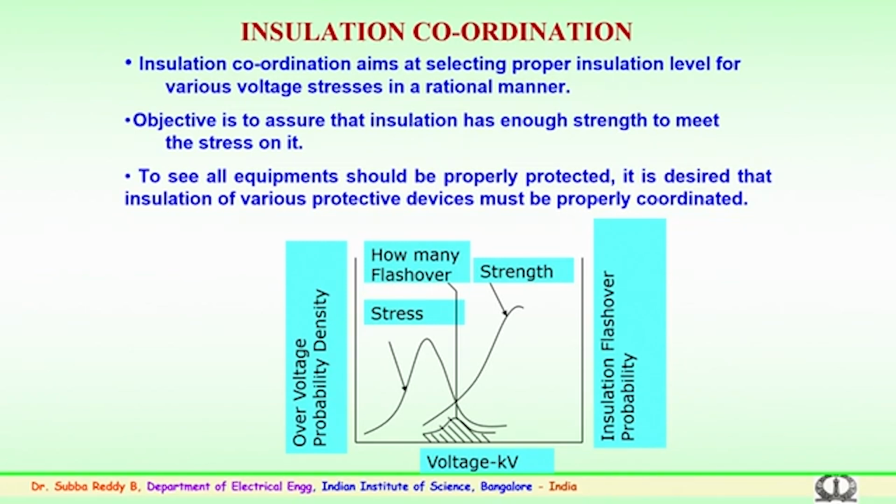In case of the stresses which we discussed, maybe mechanical, maybe electrical, maybe environmental, the insulation has to withstand them during emergency conditions. So, for all equipment to be properly protected, it is desired that the insulation of various protective devices must be properly coordinated. This is the main aim of insulation coordination.